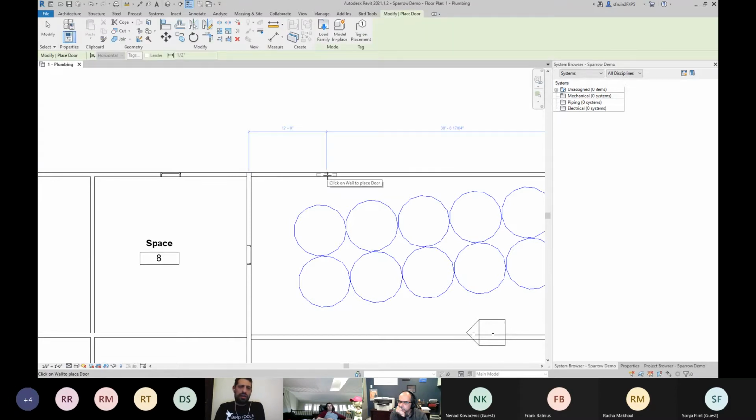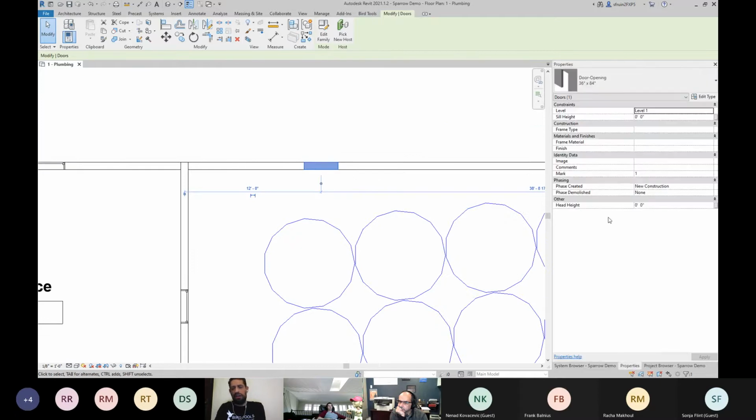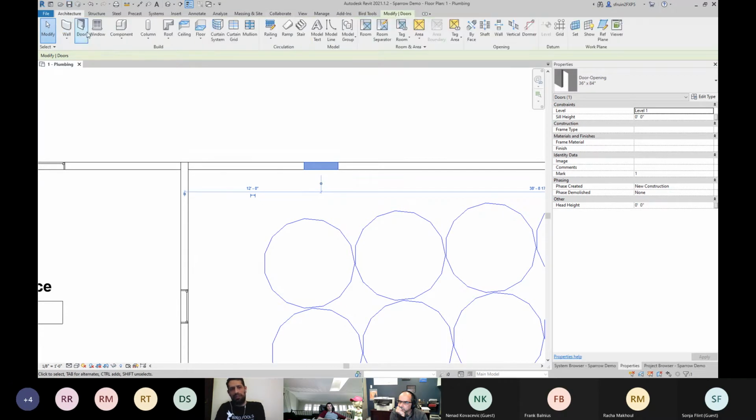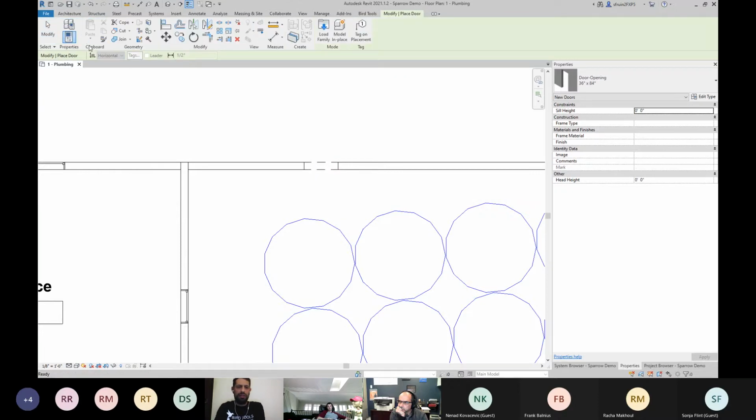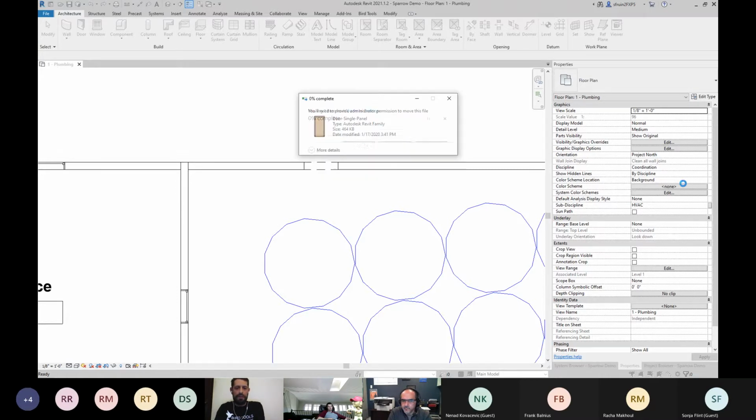Once you get the geometry object, you can cast it as a line, as a solid, or as any of the geometry classes, and check whether it's still valid. If it's not valid, then it's not a solid, it's a line. So that's one way to achieve it through the Revit API. If you know C#, you can do it as a C# node, or if you're more familiar with Python, you can do it through an IronPython script.